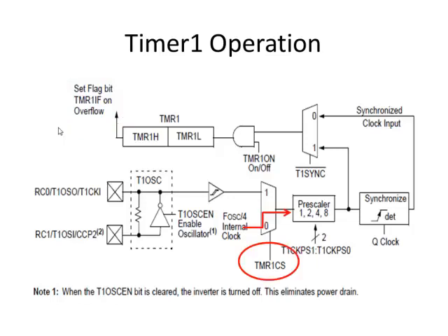Okay, our count pulses, as I mentioned before, the difference between a timer and a counter is that a timer will count clock pulses and a counter will count external pulses. So this bit right here, the Timer 1 CS bit, is the clock select. That determines whether we are counting internal clock pulses or external pulses that come in from an external pin.